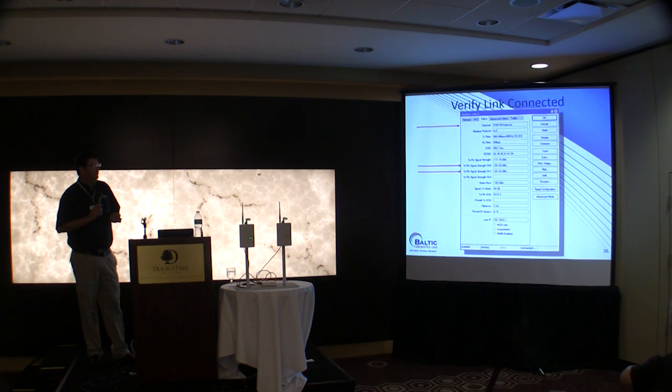So finally, after that's all done, we can go over to the status tab of our client and see if we're connected or not and how we're doing here. Here you'll see up here our channel size. We're connected to 20 megahertz channels using our center channel, and it is AC connected. In this particular case, we were doing a speed test, so it was locked up at that 866 rate.